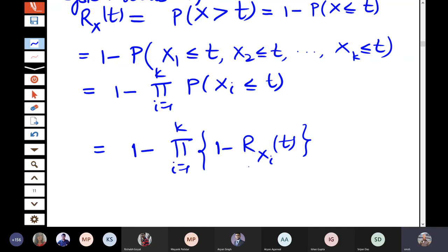So system reliability from 0.9 becomes very, very high if I have 10 components arranged in parallel. Even if I consider say 2, then it will become 0.99. If I consider 3, then it becomes 0.999 and so on. So this is the effect of parallelism, or having additional support in engineering systems. Is this clear?